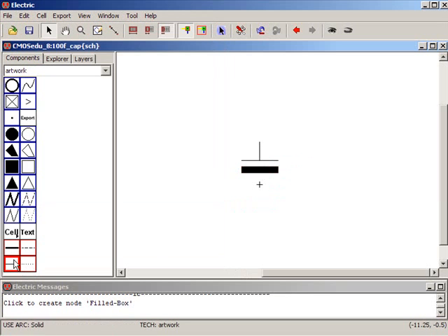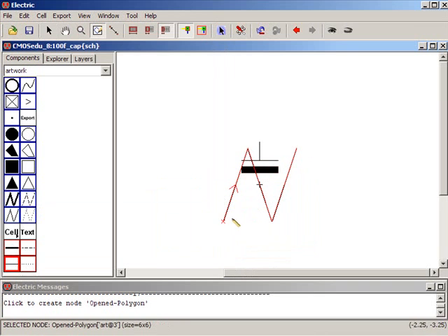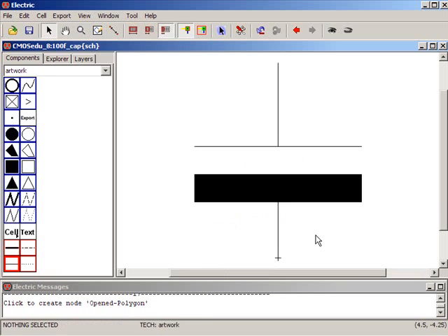And last but not least, let's put another box in here and press Y, drop this node here, drop this node there, and then we can select this node, delete, select this node, delete, and then Y to get out of the mode. And now we have our schematic for the capacitor where this plate indicates poly 1.